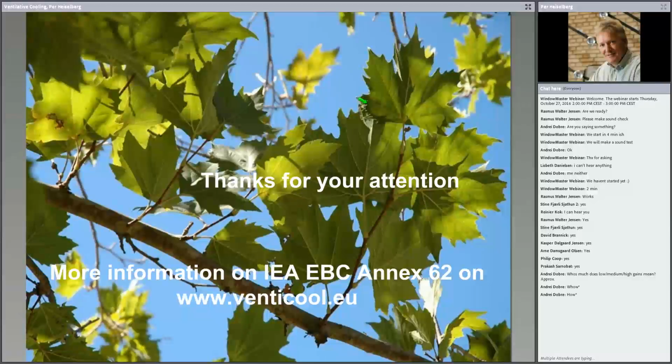Yes, I do have some numbers. If I just get 2 minutes, then I can give the exact numbers. The low gains was 13 watts per square meter. The medium gains was 19 watts per square meter, and the high gains 26 watts per square meter. And that is, of course, the internal heat gains. In addition to that is the solar gains. Yeah, of course. Okay. Thank you, Per.